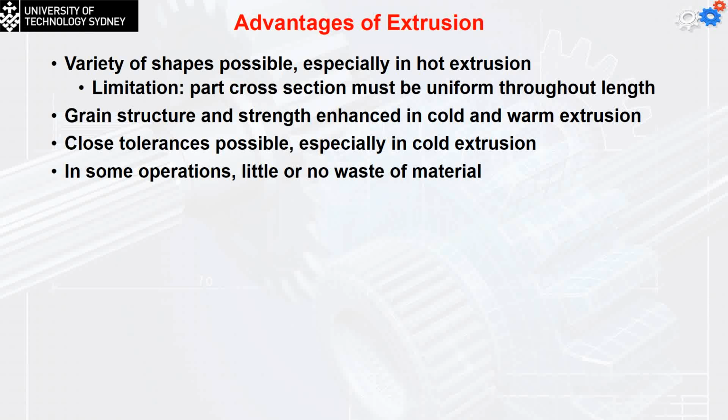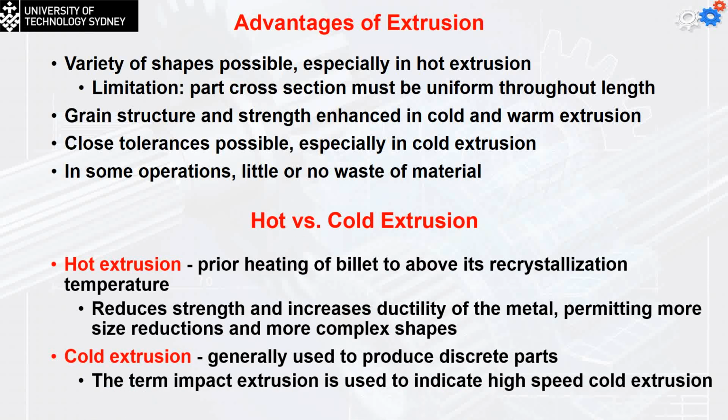The comparison between hot and cold extrusion: in hot extrusion, prior heating of the pellets is required, and it's usually above the recrystallization temperature. So does anyone here remember what the recrystallization temperature is? What was the recrystallization temperature? Half of the melting point, okay? Half of the melting temperature.